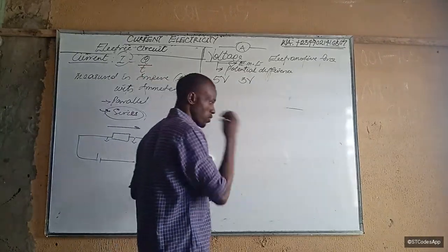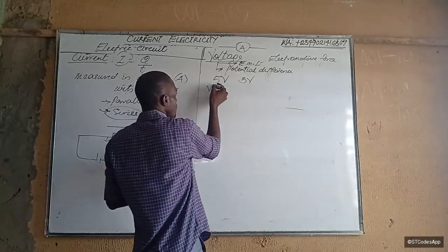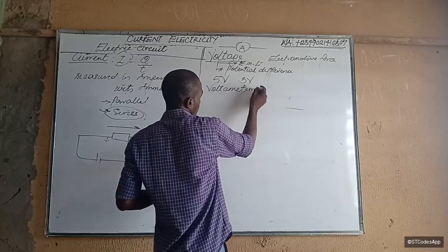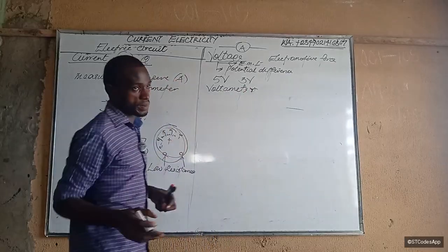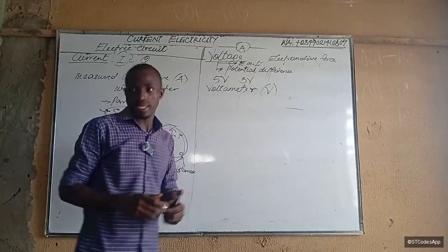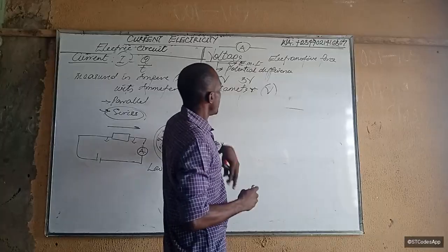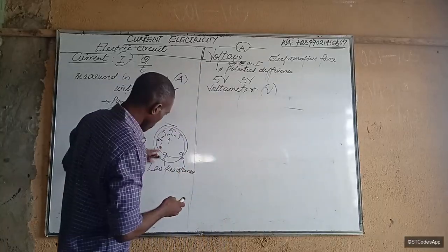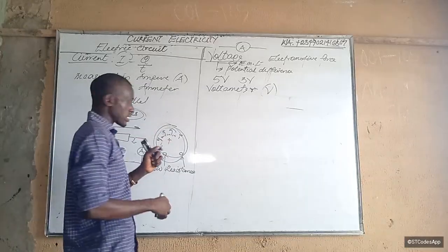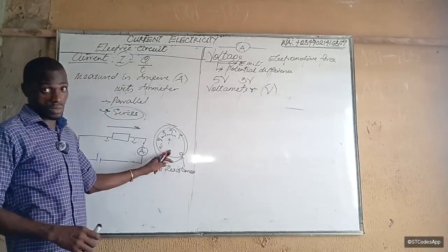Now, how do we connect it? No, let's first talk about what is used to measure it. It is measured using a voltmeter, or voltameter, that's another way to call it, but we typically call it a voltmeter. A voltmeter has the symbol V also. That's the symbol for voltage. Now, a voltmeter also has two terminals, typically like this too. If you connect it and it reads away from the zero mark in the opposite direction where there is no calibration, change the wire the same way we talked about for the ammeter.